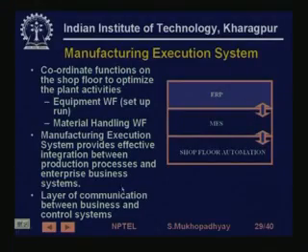So, basically, as I also said earlier, the manufacturing automation system sits between the business system and the shop floor automation. It takes the business system requirements and targets, and in turn generates the targets which can then be sent over to the shop floor automation system, which is going to actually meet those targets in terms of volume, quality and efficiency of production.